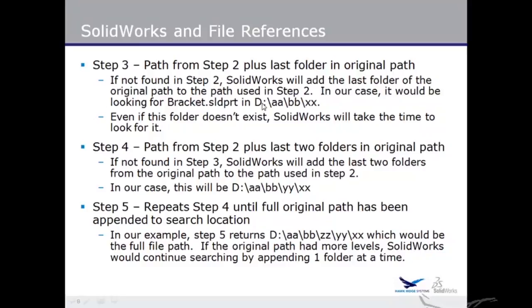So it's going to search in DAABBXX. Now what's interesting about this is that that folder may not even exist. That may be a completely fictitious folder, but even if it doesn't exist, SolidWorks is going to go out there and it's going to try to find it. So even if the folder's not there, we're still wasting time going and trying to look in this non-existent folder.